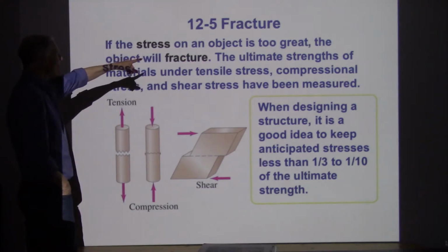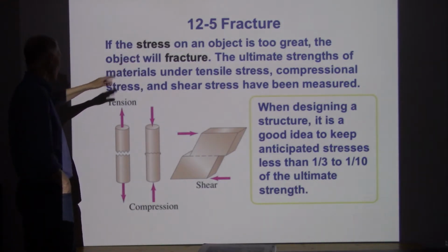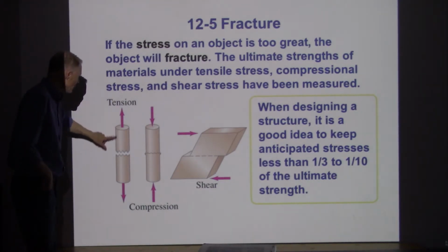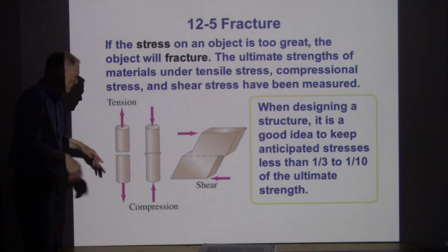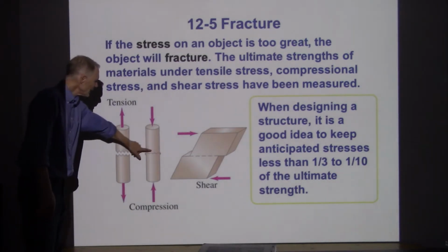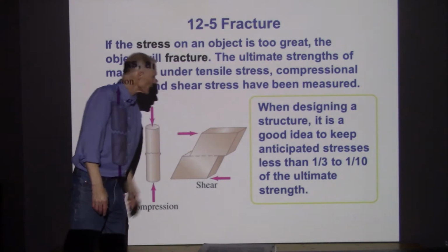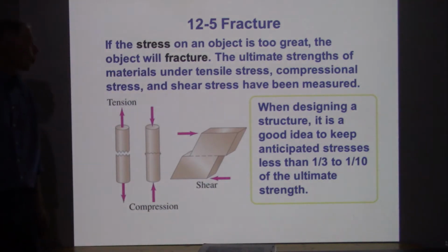Now, there's also this issue we talked about where the material fractures. It fails, it breaks. Under tension, that usually looks like the material just splits. It fractures through. Here, we start to see fracturing take place within the material itself. With shear, we can have fracturing along layers parallel to the forces.